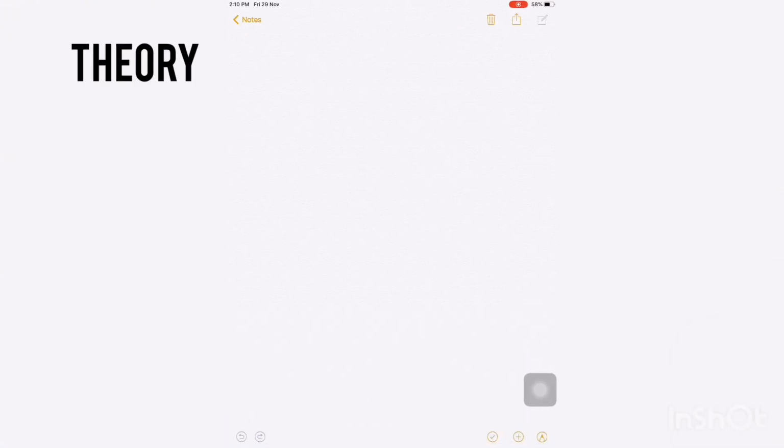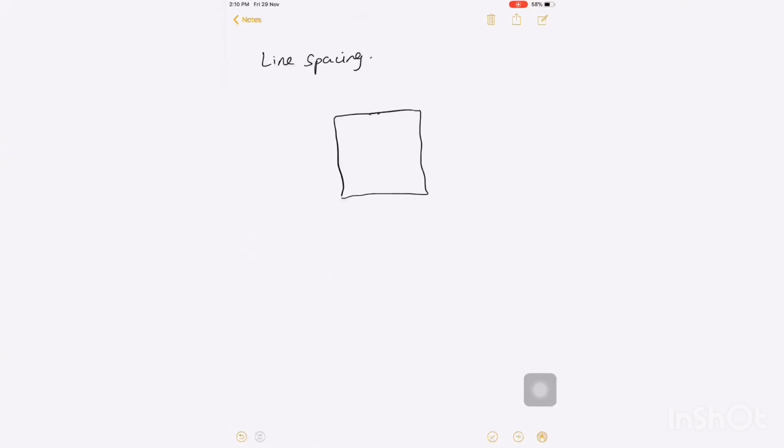Okay guys, here I will explain the different settings which I have shown you in the raft options in the Creality Slicer software. First we'll go to line spacing. To be more specific, if you see the printer from the top view, this is the printing bed. The printer starts to print once you switch on the model which you're going to print, and it starts to print like this. Line spacing is the distance between these two lines, which I have given as 0.8 mm.